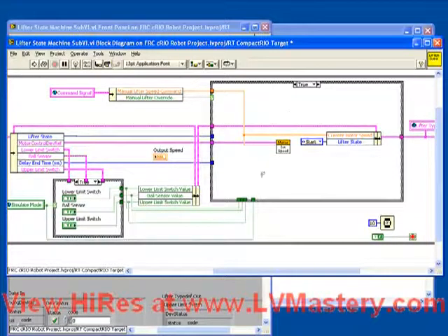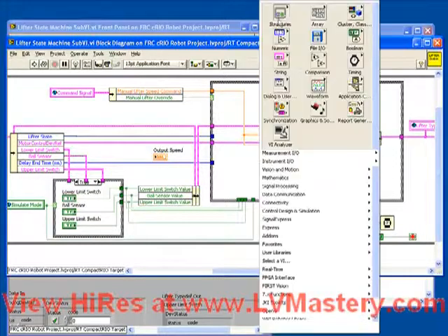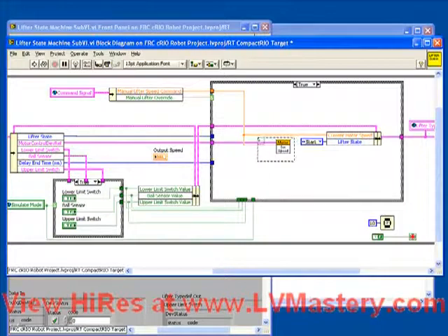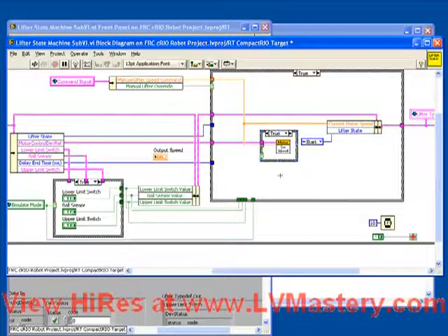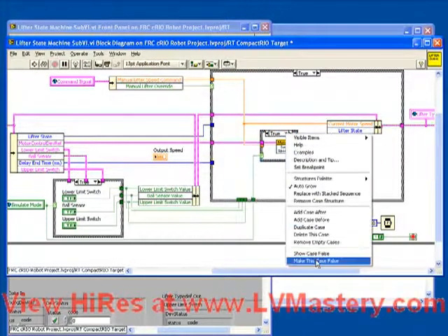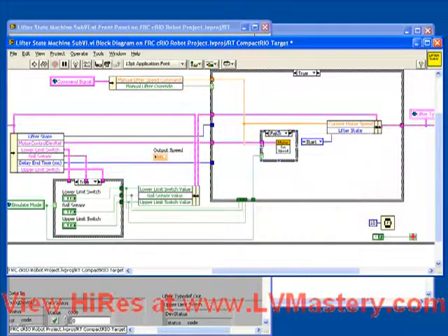All we need to do now is case out all of our motor set speeds. Put case structures around every one we find. And usually the act of doing this means you have to make a bit more room in your block diagram in order to get everything to fit properly, which often means having to clean up the positioning of wires a little bit. But again, if simulate is false, we're going to write to the motor. But if simulate is true, we're going to write directly to our output speed indicator.